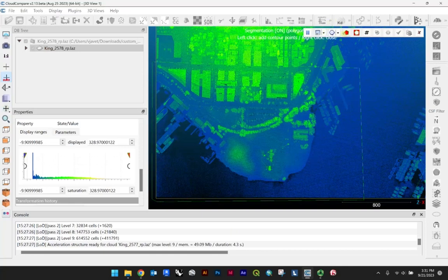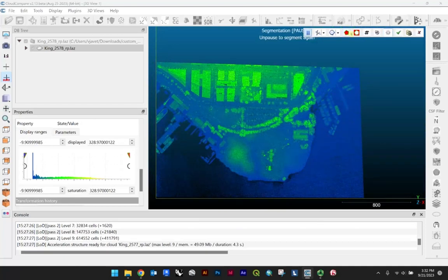From there, we have a couple different options. Like we could change the attributes, the classifications of the scalar fields again. In this case, what we're looking to do is actually segment, and we can do two things. We could segment the selected area out of the data set, or we could segment the data set itself. And what we've drawn a boundary around, we want to segment the inside of that. So I'll just give that a click. And that was this button right here. From there, we'll just go ahead and confirm the segmentation. So the green check mark.